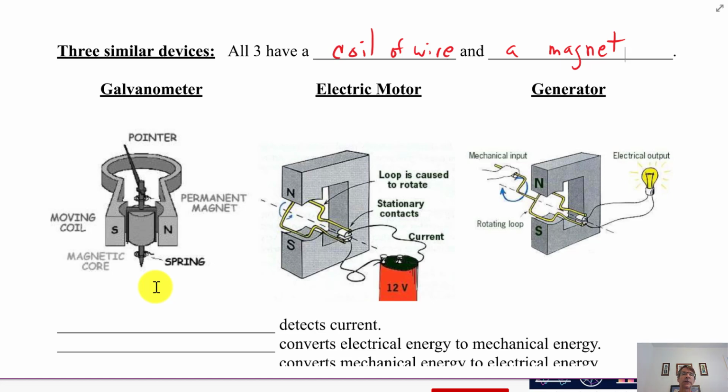And basically all those two wires are connected to is the coil inside here. If you have a device exterior, like a battery, that creates current, or you put this galvanometer in a circuit in series to measure current, current goes through this galvanometer, through that coil of wire, and when current goes through that coil of wire, it's magnetic induction.